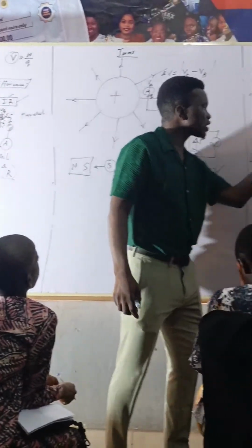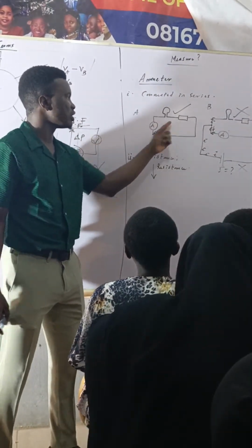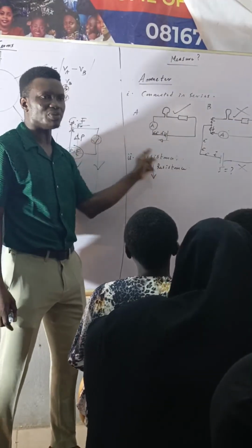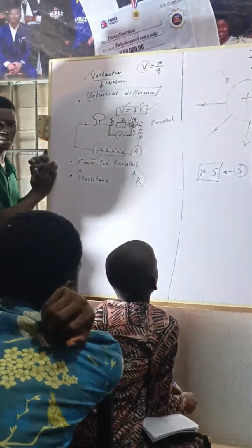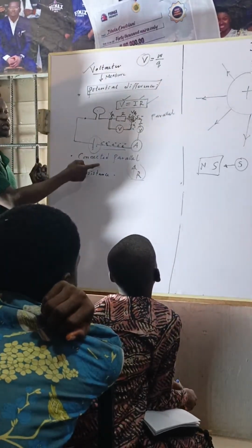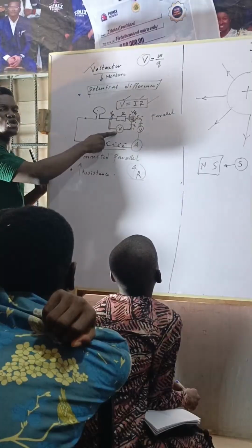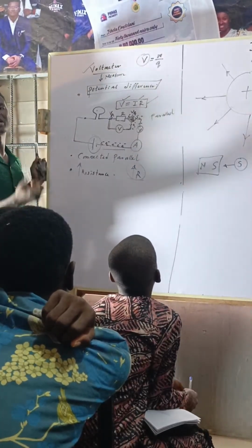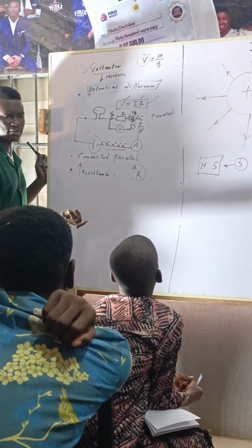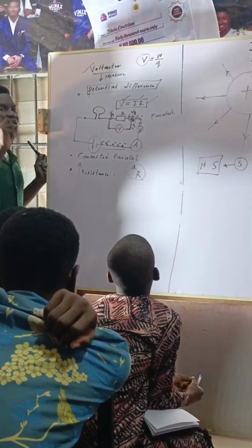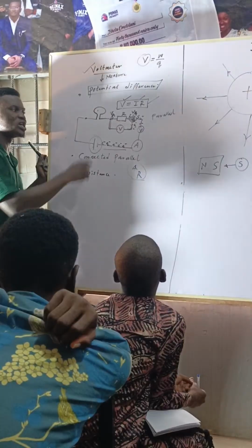So you can look at the ammeter now. Do you think I'm not trying to measure from here to here? That's why I want to know what is going on. So if you're listening, that should be understanding. So do we all get it now? So your voltmeter must always be connected in what? In parallel. And the resistance in the voltmeter, should it be low or high? Why are we making it high? To prevent the flow of currents through the voltmeter. It is still that current that will cause the deflection. At that level we talk more about that. So it still needs current.